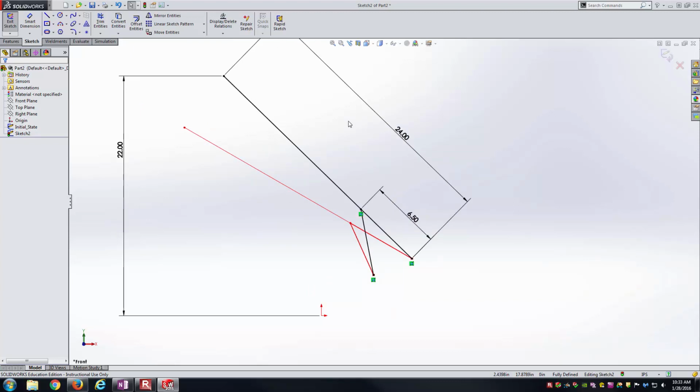And so it's nice in SolidWorks that everything is very loosey-goosey, if you will, as it is underdefined, and you can just kind of move things as needed, and then you're just applying either the geometric relations or the dimensions as you know them in order to fully constrain your sketch. Obviously it's going to be important to fully constrain or fully define your sketches in order to make sure you have the appropriate geometry laid out.